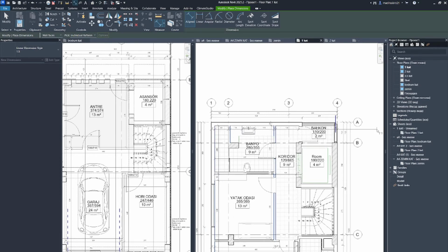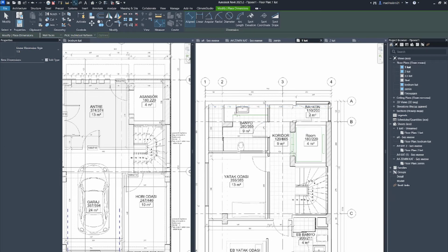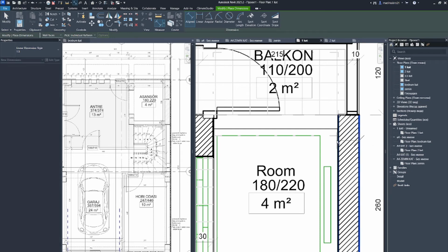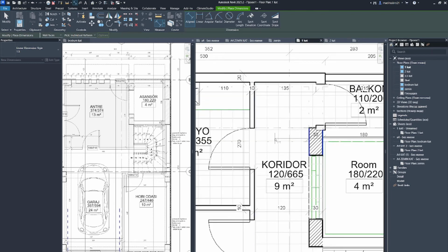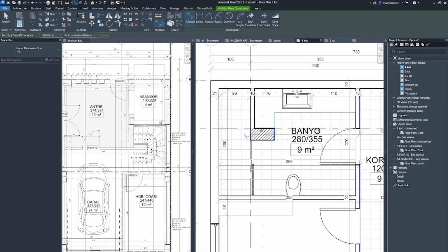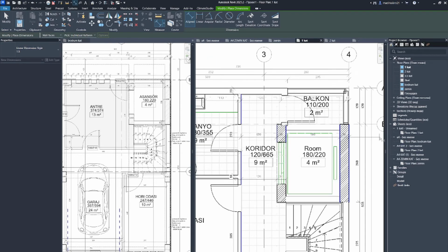I do it manually because if I use the whole wall, as you can see, it will take just a wall. Like wall faces, center of core, wall cantilevers, faces of core. This is not what I want, so I do it manually. Okay, here we finished. Now what I would like to do is also show the elevator. So I come from here and I show it, as you can see, 180. And here's another rule about the hole, that it should be not less than 120 centimeters, as you can see, not less than 120. And I come here, I would like to show this column, then again this inside, and yes, I will stop somewhere here.